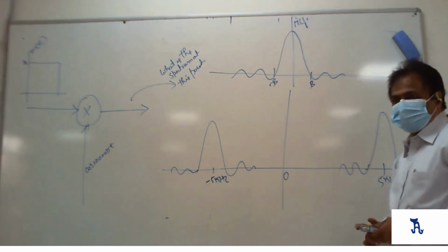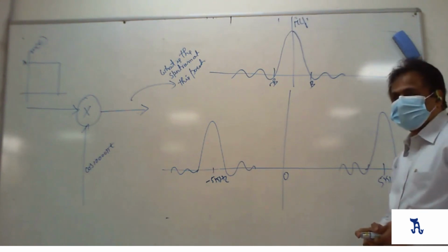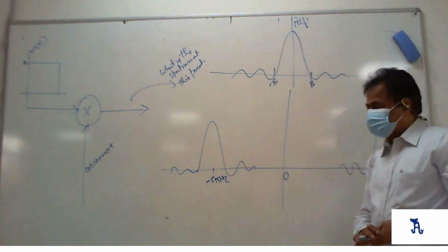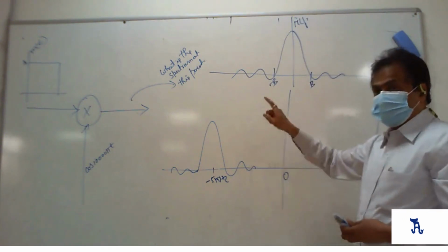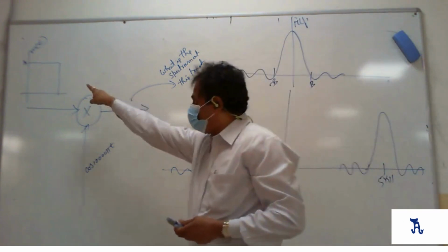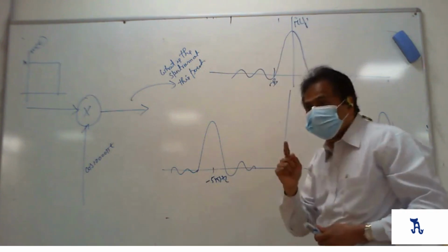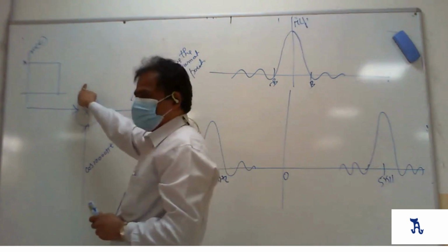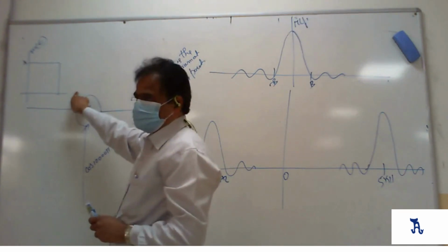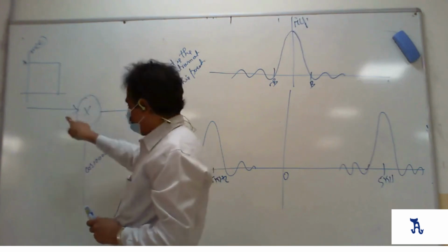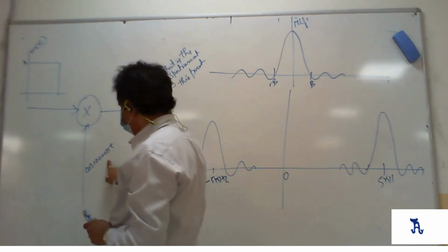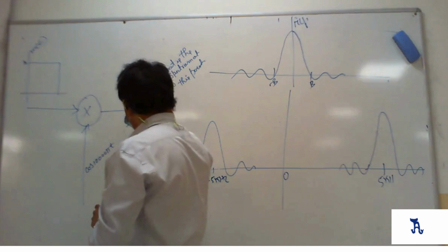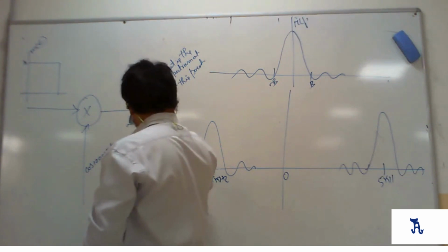Of course, amplitude will change. Definitely amplitude will change, but that amplitude change depends on the signal here. You have to solve that problem. In this case, M of t is 4, right? In this case, cos 10,000 pi t. Now tell me 4 into cos 10,000 pi into t.